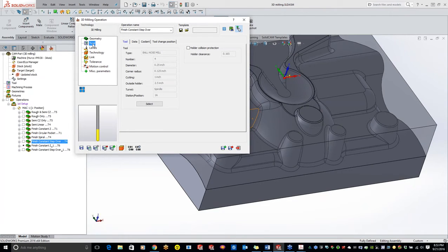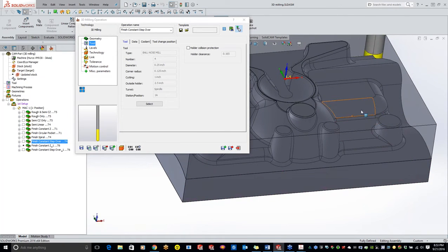No, what you'd have to do is, Dwayne, I guess you would be asking if you're doing a finishing on the entire part and you just want it to go slower over a certain section and then speed up as it's gone over that section. Unfortunately, we don't have that in there. And I don't even know if that's possible. I would have to talk to development and get back with you, Dwayne, on that one. But as it's right now, it's a constant feed rate going all the way through, so that feed rate isn't going to change. The only time that feed rate does change constantly is if you're roughing it out using 3D iMachining. So 3D milling.